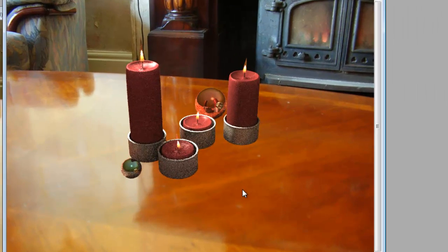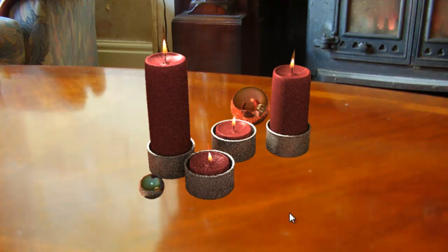Now you can see there are a few drawbacks with just doing this straight masking, because this surface is quite reflective, but it's not reflecting any of the group. And these volumetric candle flames, you can see that it's masked the shape of the object, and it's not obeying the shape of the volume flame. So it's left these points on, which is a bit odd. Likewise, as far as the lighting is concerned, it's not really a bad match, but there are no shadows. So this group does tend to look a bit tacked onto this image. So that's your most basic way of masking in.